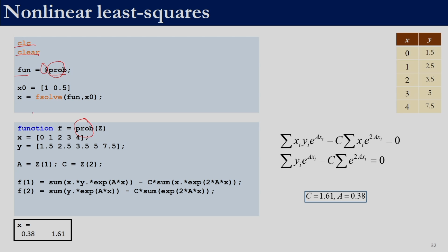For solving nonlinear equations in MATLAB, you can use this fsolve command. For fsolve we need to give the equations that we want to solve and the initial starting point. Here we have two variables, and we are going to arrange them in this format: the first variable is going to be a and the second variable is going to be c.